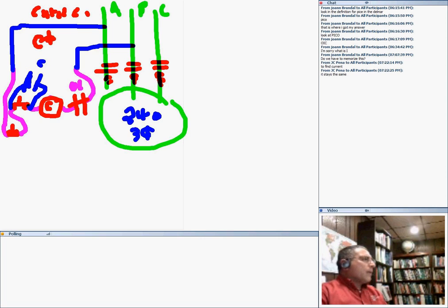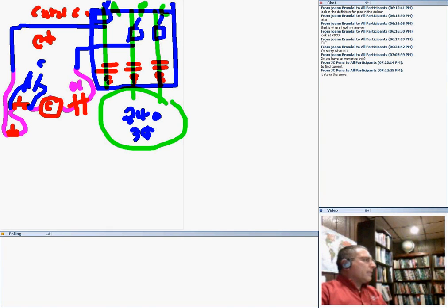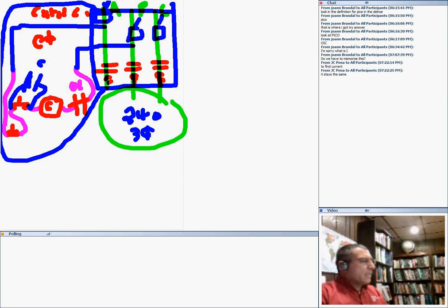That's for a three-phase motor. And of course, I don't want you to forget that there will be your overcurrent protection device right in here with the disconnect. That's your fuses. These are your contacts and all that, as well as the stuff right in here. These are called NEMA starters. That's what you're looking at, a combination NEMA starter with disconnect, overcurrent protection device, contactor and overload, a combo starter for a three-phase 50 horsepower motor.